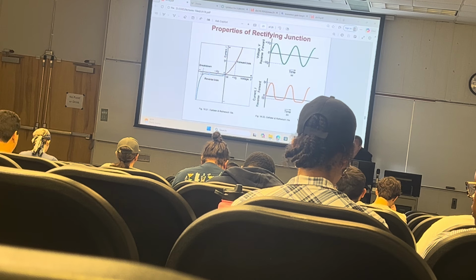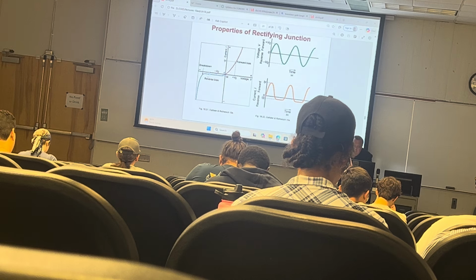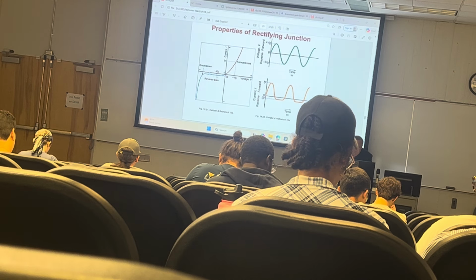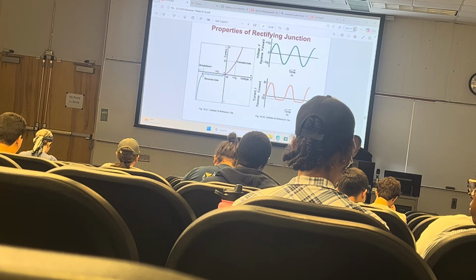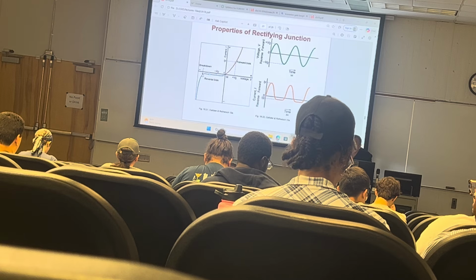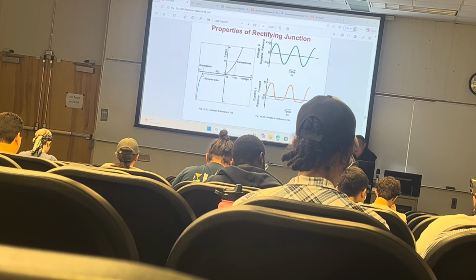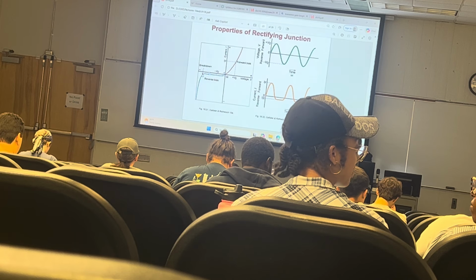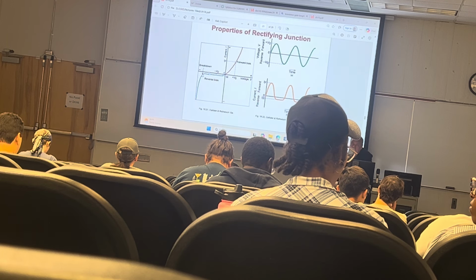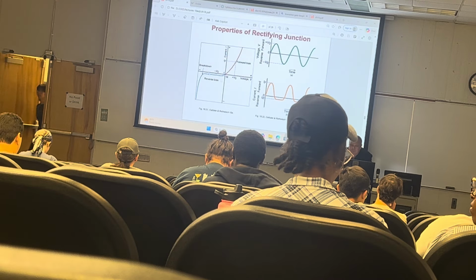There's a breakdown voltage, meaning that if you are increasing the negative voltage, then eventually it's going to break down and it burns. Does that make any sense? So the diode is rated for the voltage, if you look at it, and it's rated for the current. So you need to match for your specific application, making sure that it doesn't get too hot, that it doesn't get reverse blown.